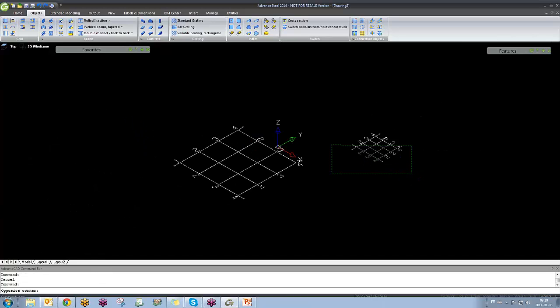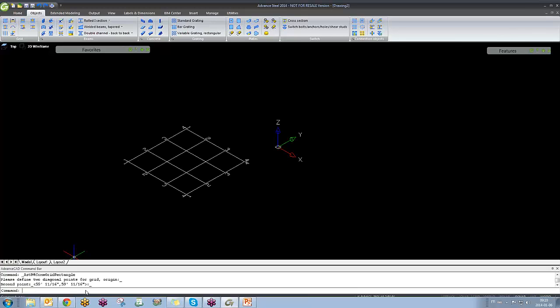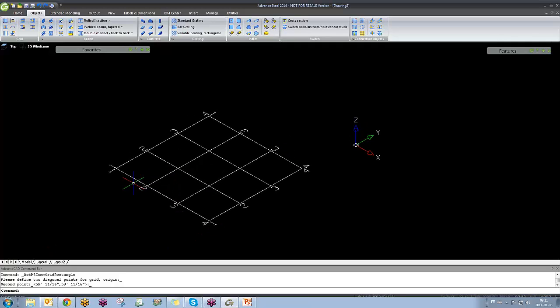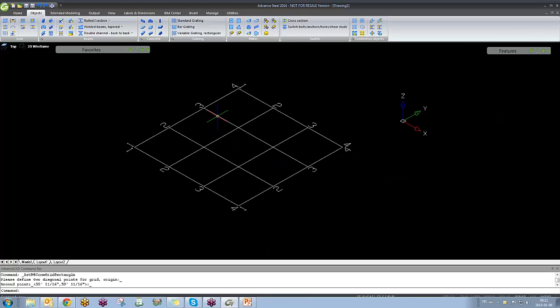Yes. I will delete them. You only have to select this standard grid tool and click. If those values are doing the job right, hit enter. If not, just enter your own diagonals, your own values. Now, once the grid is created, you should modify the values of the intervals, the distance between the axes.